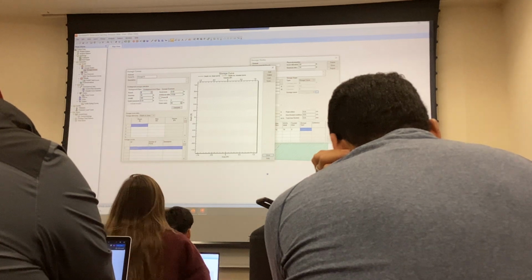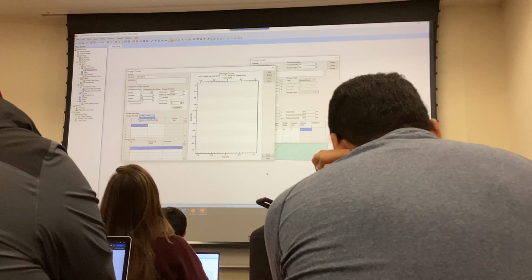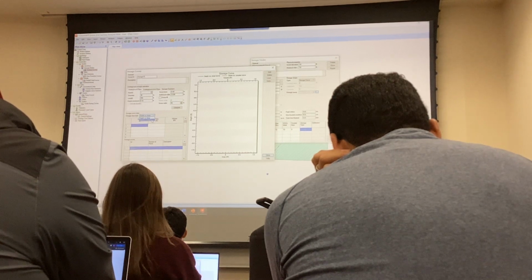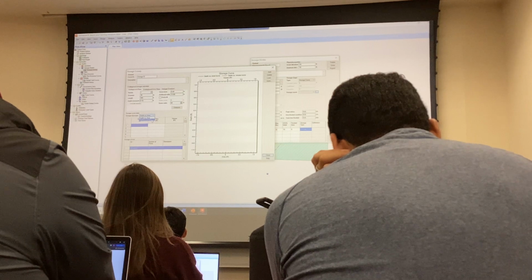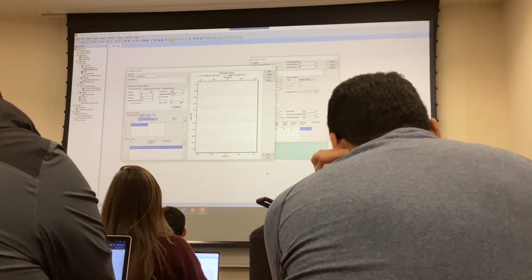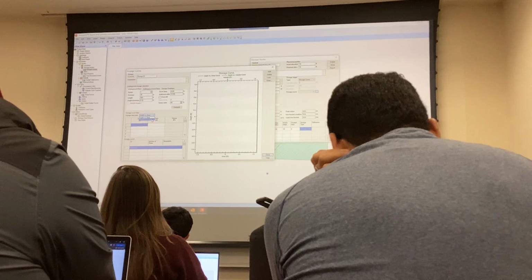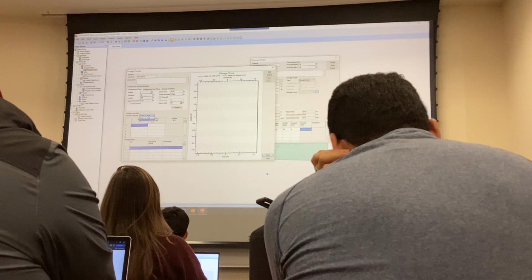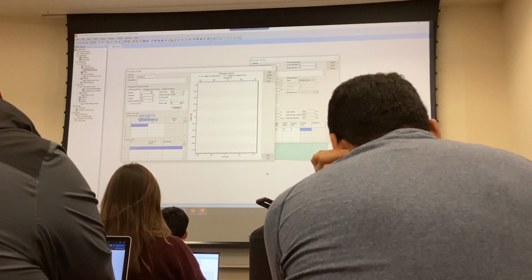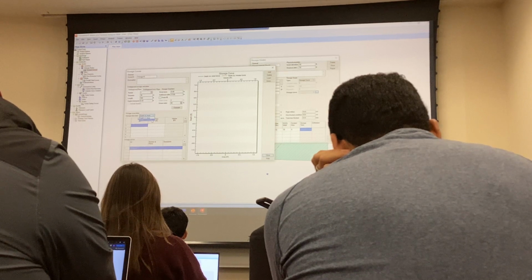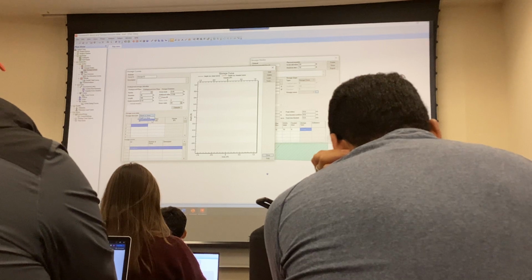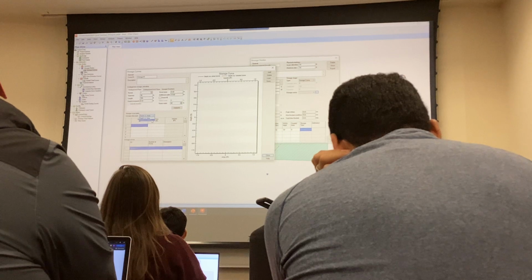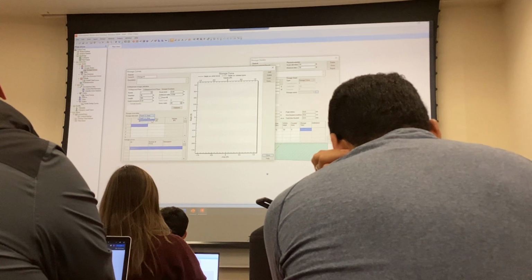So you want to come over here and choose between depth versus area or depth versus volume. In any case, you are going to have this information after you grade your detention basin, which is why it's important. Once you get the volume that you need, you start grading because you are going to be pulling up this area versus elevation, or area versus depth curve and information and put it into your SSA.